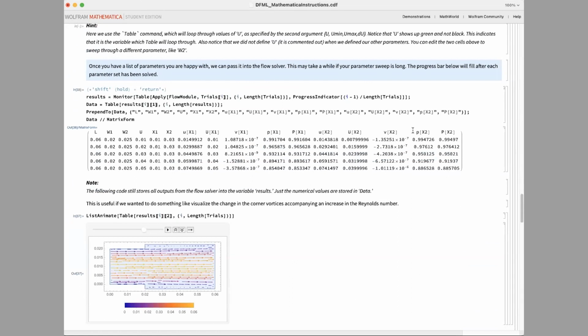So before, when you saw that our first output from our results function was a bunch of numbers, here we assign them to the variables. So we have our channel length, our widths. And this is relevant once we start varying the aspect ratio, the input velocity, where we picked our 2 points, our point and averaged velocities and pressures.